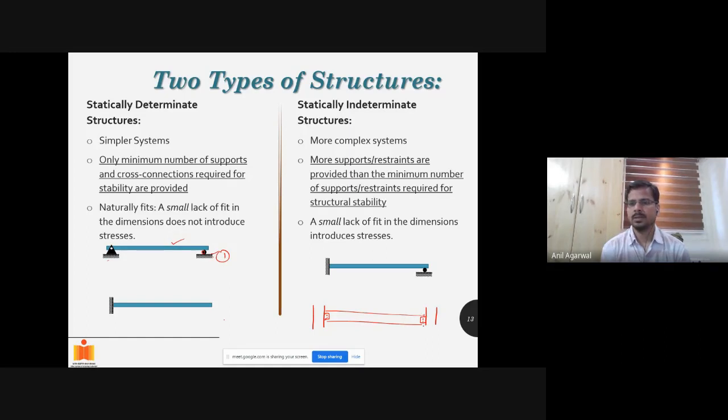Then I bring in the beam, and the beam also has holes. The holes of the beam are supposed to match with the holes of the angles that are welded to the column. If these angles are stiff enough, and the columns are stiff enough, we can idealize that as this kind of a system.